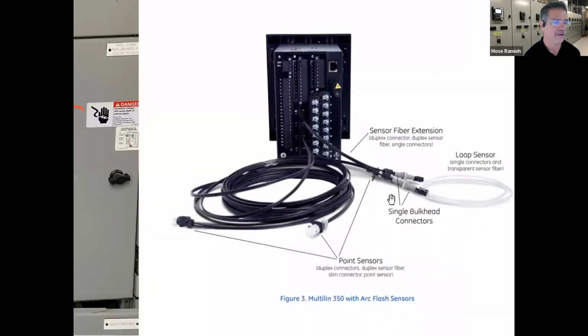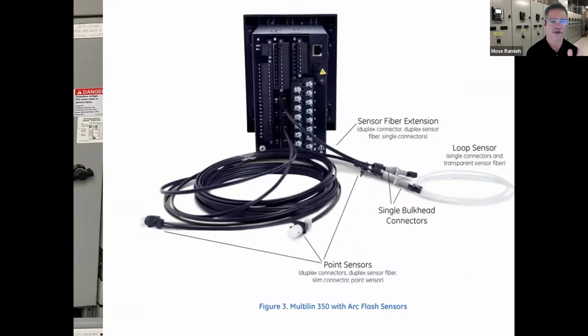Maintenance. And then once again, a lot of manufacturers are coming out with some great products to reduce arc flash and to almost eliminate arc flash hazards altogether. They can't technically say that on your label, right? But if we install a relay like pictured here, with fiber loops and point sensors installed along the buswork or in the cubicles of the breakers, then it's taking into account two factors. It's looking for fault current and a flash of light, which is a precursor to the arc flash, right? You'll see that flash of light.